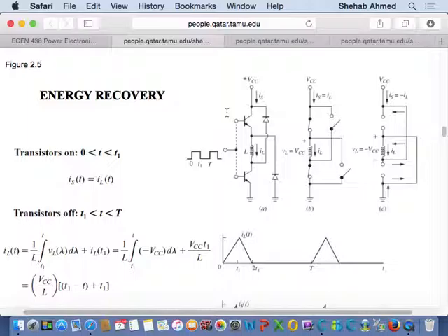But then there were a lot of people also working on, they want to optimize power converters to the limit, right? So they want to figure out a way to recover energy. If you have an inductor circuit like that, like a relay that we just wanted to turn on, it's power loss, right? If I'm going to dissipate this energy that I stored in the inductor into the resistor, I'm losing some power, right? It's not a big amount of power, for example, in a simple relay circuit, but let's say you have a battery-operated device and you want to be able to optimize power consumption as much as possible. What would you do? You would try to tweak your circuit to be able to recover as much energy as possible.